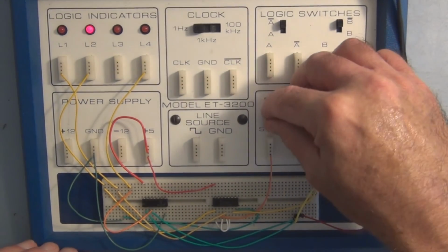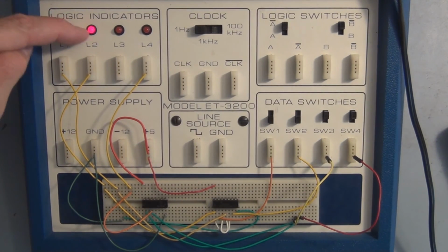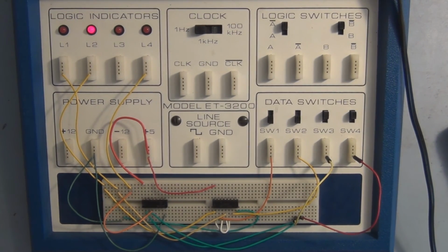I think if I try hard enough, there, I've gotten this to be the opposite. But that's an illegal condition with this very basic NOR gate flip-flop and flip-flops in general. Because by definition, again, the outputs are opposite each other. Two outputs opposite each other. But you can see there I've demonstrated the memory condition that this circuit has.